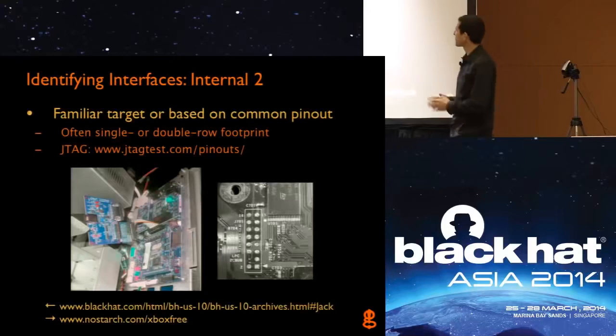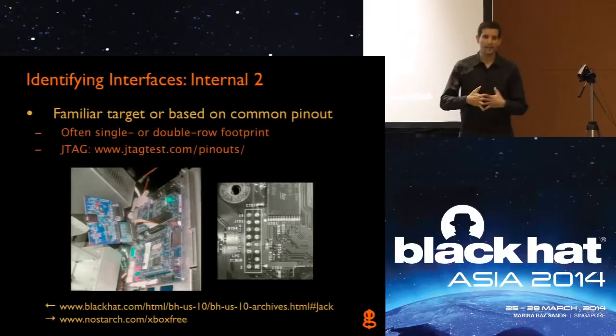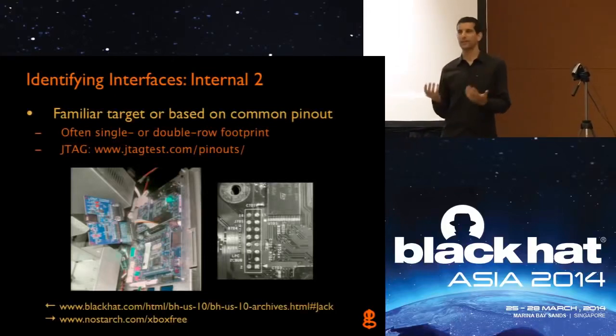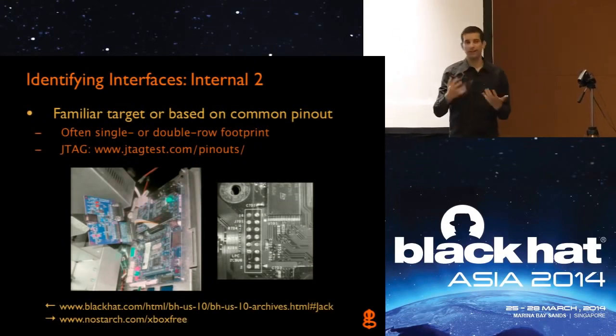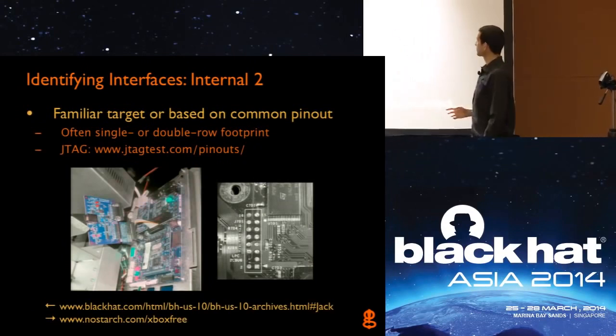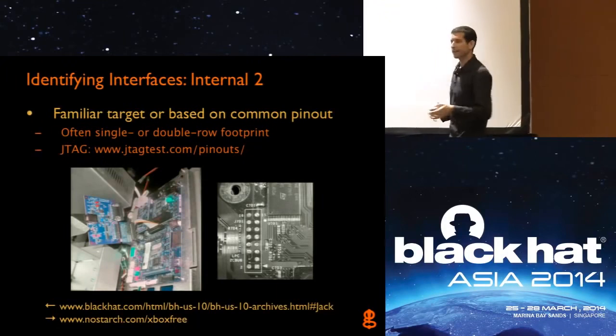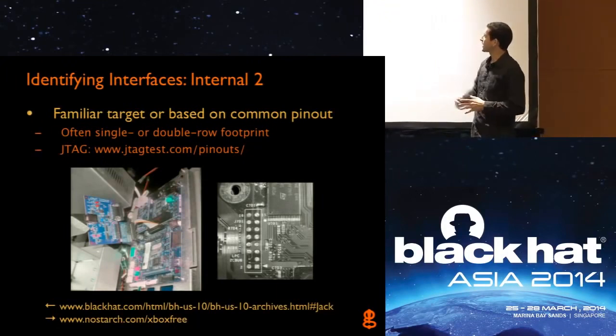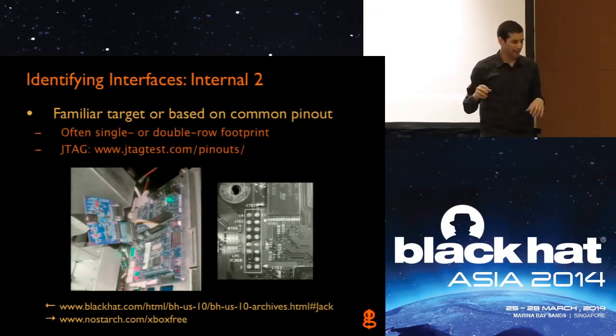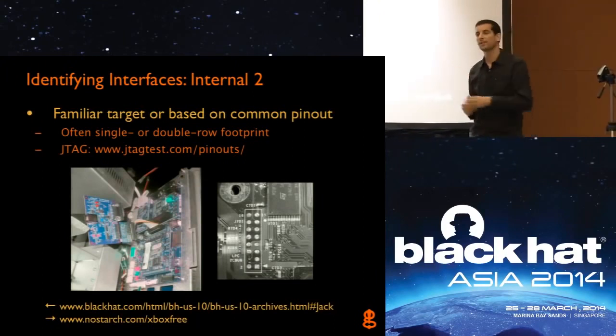Other times, the pinout is based on a common format or maybe an industry standard format. So it's not just a bunch of random test points or an unknown grouping, but something where you can go online and verify pinouts. Sometimes it would be a single row pinout, sometimes double row. The most commonly used would be a JTAG interface, which again, we'll talk about more later, where you can go to this website, jtagtest.com, and look at different common pinouts for different architectures.